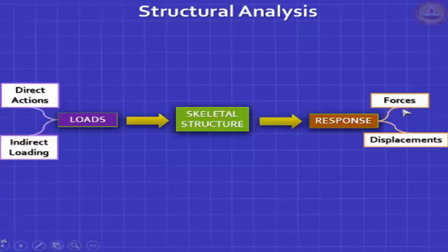At any section, at all sections, you capture them by drawing the shear force diagram and the bending moment diagram. And there's a displacement response, which means deflections, slopes, curvatures. The curvatures must be matchable to the bending moments. So you should know the big picture. This is what we need to do.